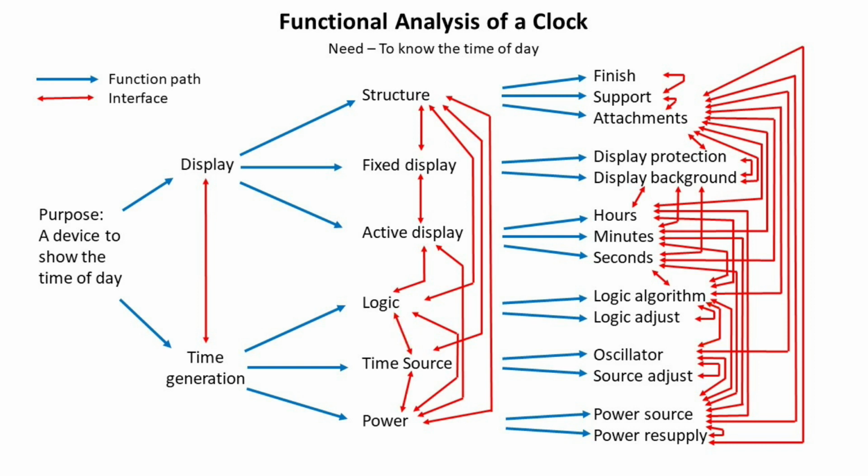There are a few things to note here. This functional breakdown applies to any clock, from a wristwatch to a town hall public clock, which is fine up to a point, but to move to a system design, we're going to need other requirements like the interfaces, the environment, and such like. And that said, notice also how the system design decisions are creeping in. The timer is going to be some form of oscillator. Alternatives like receiving GPS time signals are being ruled out, and that is not a logical consequence of the functionality alone. We've also made a design decision to show hours, minutes, and seconds.